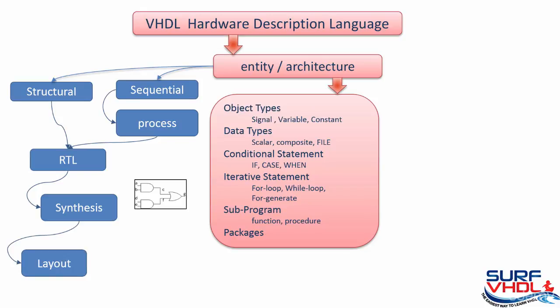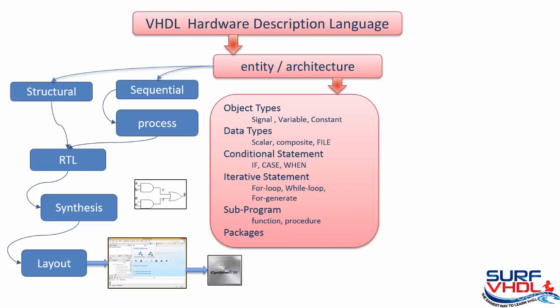The structural netlist is the input of the layout tool, in our example Quartus, and connected using the hardware resource in order to logically implement the VHDL design. In our course, we will use an FPGA using the Altera DE0 board. The RTL is the coding style used to implement logic inside a silicon.